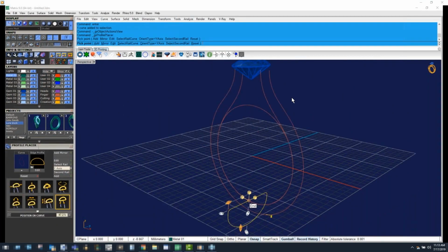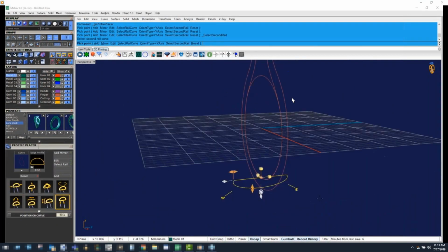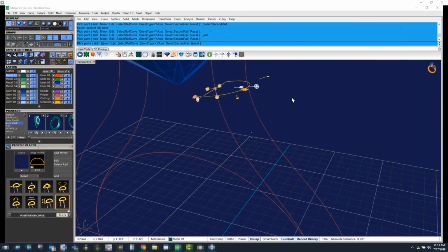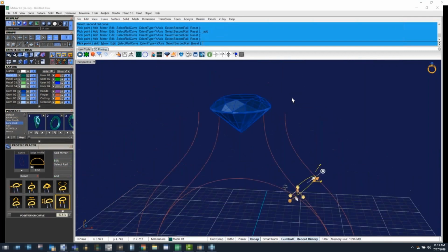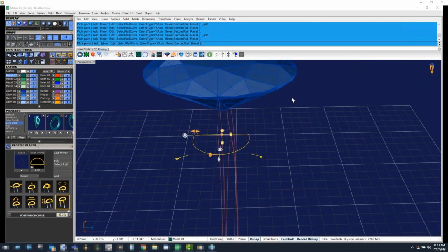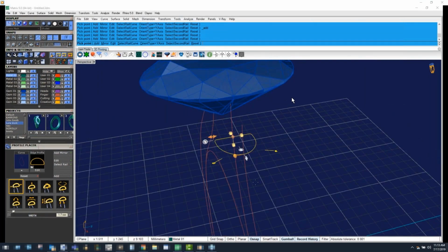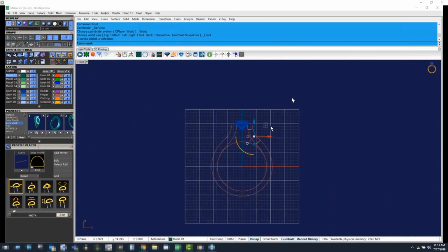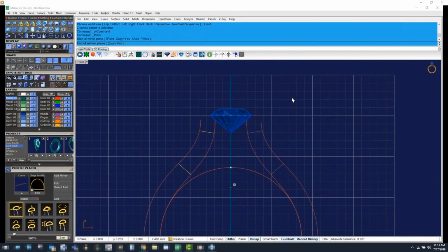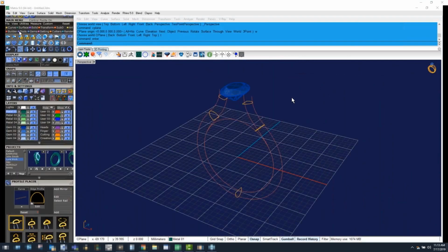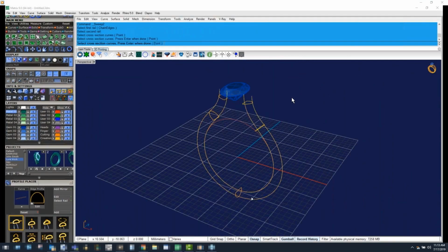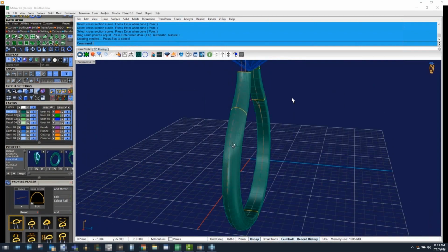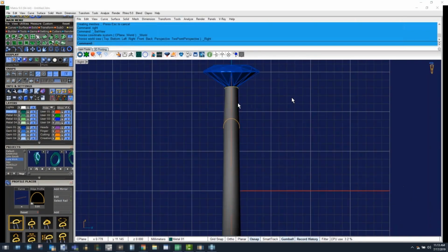And then I'm going to put profiles on those ring rails and sweep them, right? So as I said, I kind of want to taper, so I'm going to use 3 different profiles and kind of taper it up. And now I need to mirror them over to the other side to complete it, right? So I'm going to sweep 2, select my profiles, and complete the sweep. And you can see I have a nice taper.